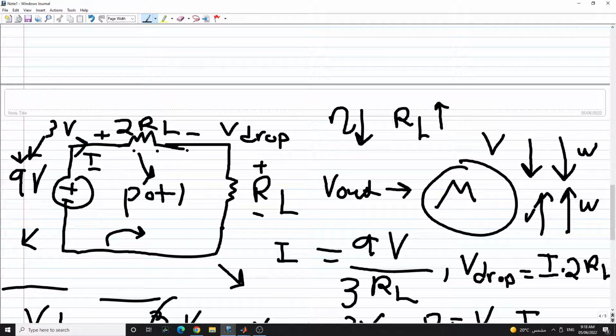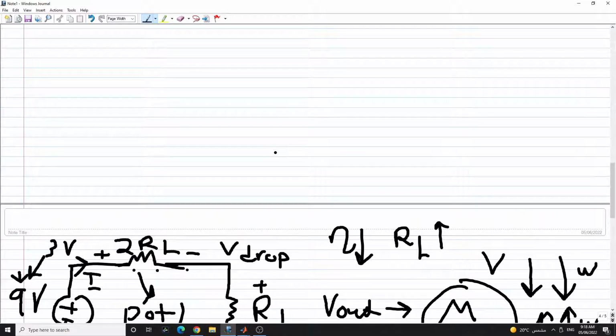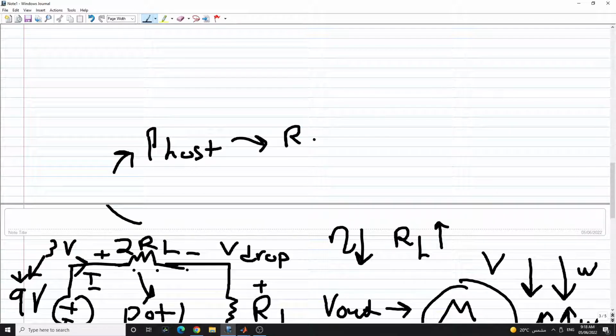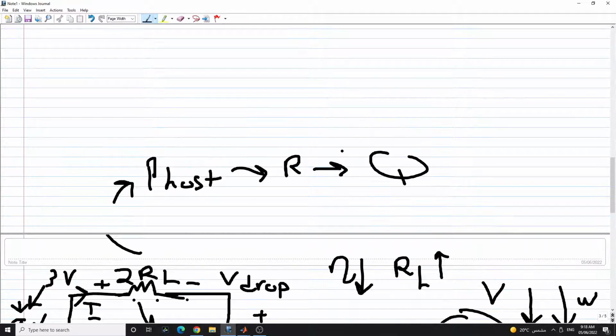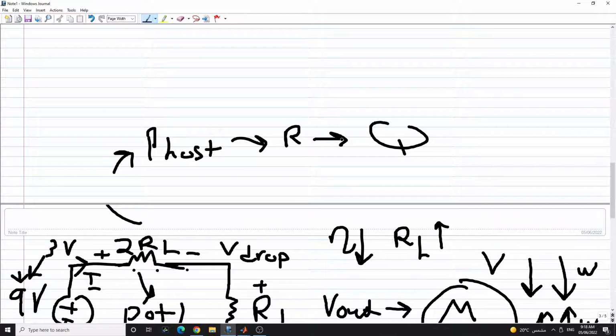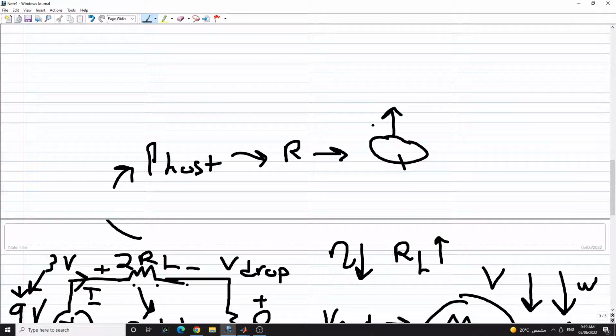And now there's even a second disadvantage here. It's actually quite critical, and that is any current or any power being lost over this resistance is transferred into heat at the end of the day. Any power loss over any resistive load whatsoever, not just in electric circuitry, even in mechanical systems. If you have some sort of damper to act as some sort of mechanical resistance, you're going to end up having heat being generated in this resistive component. And this heat can easily damage our components.